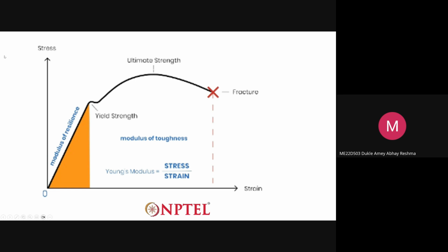I'm not talking about less force per se, less incremental force. Earlier, if you had to apply 10 newtons to get 10 millimeter of deflection, I'm just giving you an example, after the yielding point, you have to just apply like 1 newton to get 10 millimeter of deflection. So that is how you can see the changes happening.